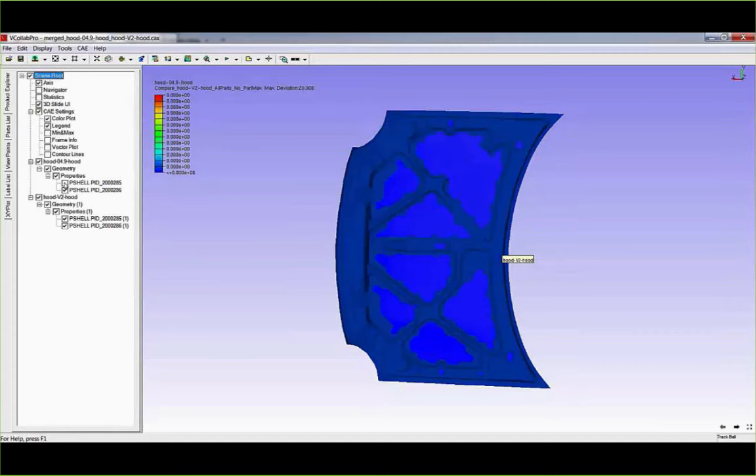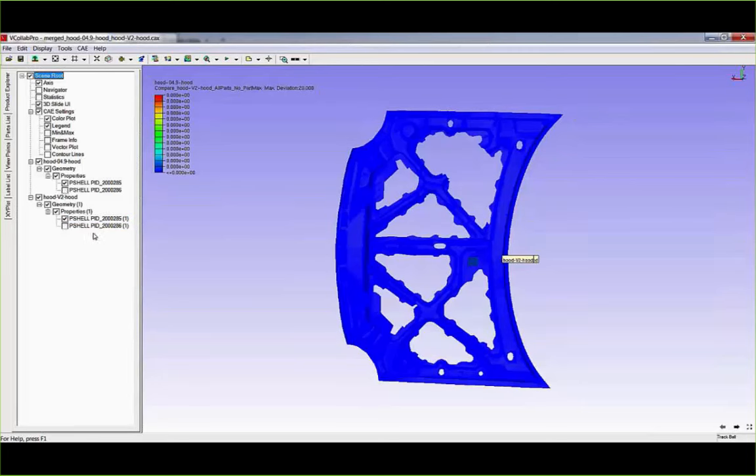Probably the defeaturing was done in this case. The hole existed in CAD and it was ignored during the meshing. So he can immediately know what changed and what are the differences between the mesh and the source CAD.